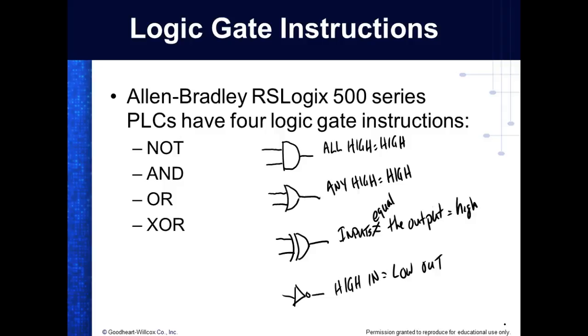Digital logic, we're dealing with voltage level flow here on the input. For PLCs, we're not actually dealing with voltage levels. If we look at these registers, we're looking for digital information, 1s and 0s. Now, on an input, if you got a high coming in or a voltage coming in, you're going to get a 1.